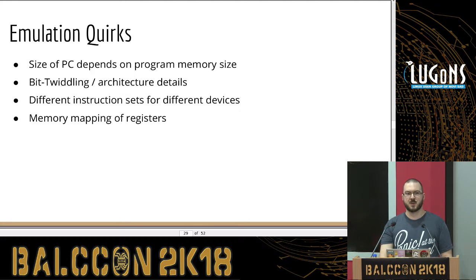And yeah, the memory map. Since you'll have to access the status register for storing some data during emulation, and the status register is in I/O space, you'll have to know whether the registers are memory mapped or not, because the registers would be the first 32 addresses in the memory space if they are mapped, and then comes the I/O space. But if the registers are missing, the I/O addresses shift by 32. So you'll have to take care of that too.